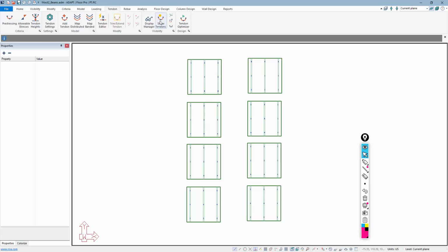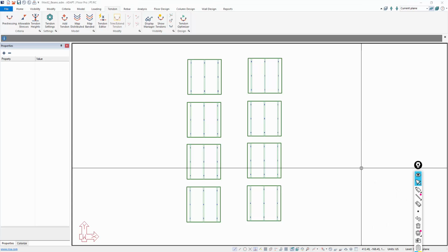The only real difference here, aside from just assigning the modulus of ruptures in any really user-defined way possible, is that the beams here will actually show loss of stiffness also, which is a good indicator or prediction of the change in the modulus of rupture, an indirect kind of predictor of that. So in this case, we'll run the same process. We're going to analyze design sections, run crack deflection, and then we can show those deflection results either again in contour form. We can also show them on beams separate of contours, and then we can also show the loss of stiffness values as well. And we'll do all three in this run.